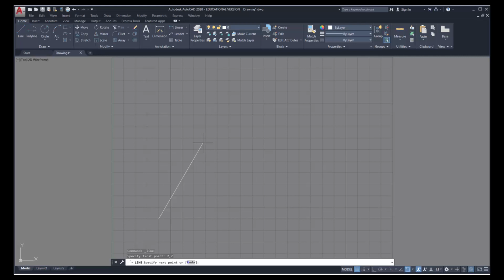So in this particular case, we're starting at the bottom left-hand corner of the drawing. We're going to go in a clockwise direction. You'll notice that the next input point is 2, 6. And that's the way we type it in, 2, 6, and press enter. You notice I didn't have to restart the line command. I'm already in it. And as I'm in it, it will allow me simply to type in these coordinates. And you can see it's following the grid. As we move in that clockwise direction, you have 4, 6, and then 6, 4, and so on and so forth. So complete the drawing as we work through.